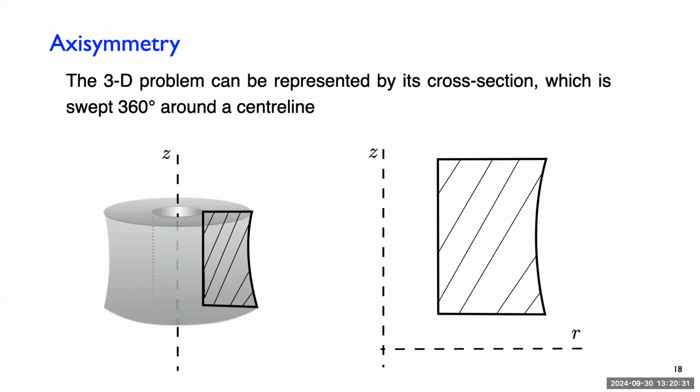So it's independent of the circumferential coordinate. It's only a function of the radial coordinate and the axial coordinate. So it's actually a 2D problem. Axisymmetric problems are 2D. They're a special class of symmetry where you only have to solve what happens on a slice, and then you know the solution anywhere is the same as any other slice. It's just rotated around.